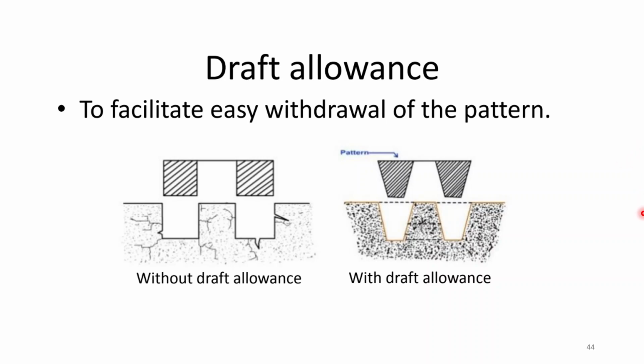So for that you choose a shape which is tapered. In case of a taper, when you remove the casting, it is very easy to remove. In ice cream as well, you sometimes see ice creams are tapered, for easier removal from the mold. The same concept is followed here as well, because in this case with a little force you can get away from the walls, but in the straight case your walls will be in contact for the entire range.